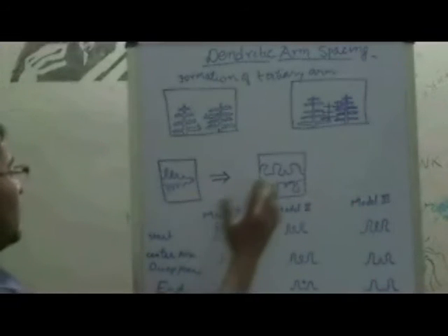Now we discuss dendritic primary arm coarsening. Primary arm coarsening is explained by three models: Model 1, Model 2, Model 3. Model 1 says that the radius of the dendrite is considered to be constant, suppose it is A, except for one arm whose radius is R0, which is less than A. The melting point of the smaller arm is less than the melting point of the others.